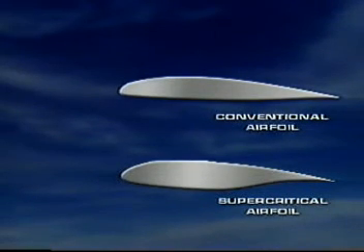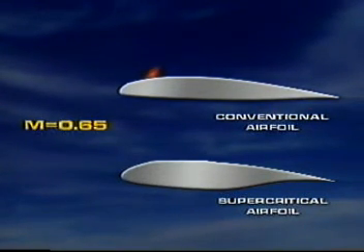Observe the conventional airfoil, normally used on turboprop aircraft, and then watch the supercritical airfoil, normally used in high-speed applications. The latter is characterized by very little camber in the forward portion. On the other hand, the rear portion is severely cambered. See what happens when forward speed increases. Both airfoils flying at the same speed. The shock wave appears first at the conventional airfoil and is delayed and weaker in the supercritical airfoil. Hence, compressibility drag is delayed and weaker for the same speed. To reduce additional drag, jets have swept-back wings.